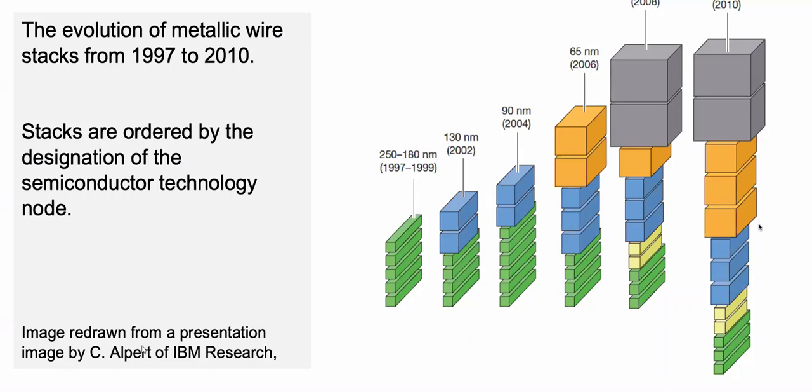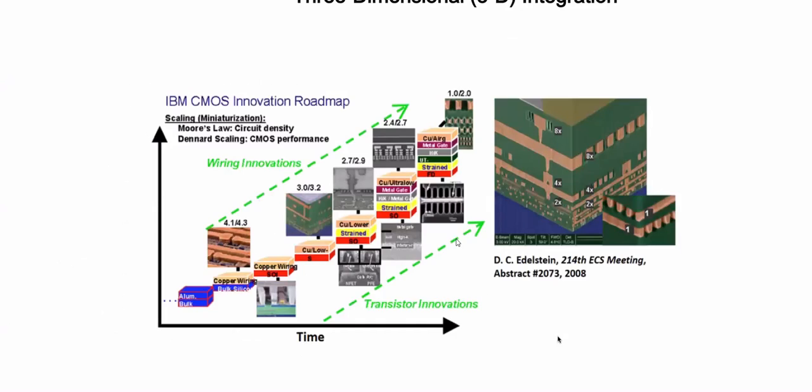In 2010, they have 13 layers. And green interconnects, yellow, each one has a purpose, each one is a different design. And if we talk about less than 10 nanometer metallization, we also need ultra thin barriers: which technology to use, which conducting materials. So there's a lot of material science also involved.